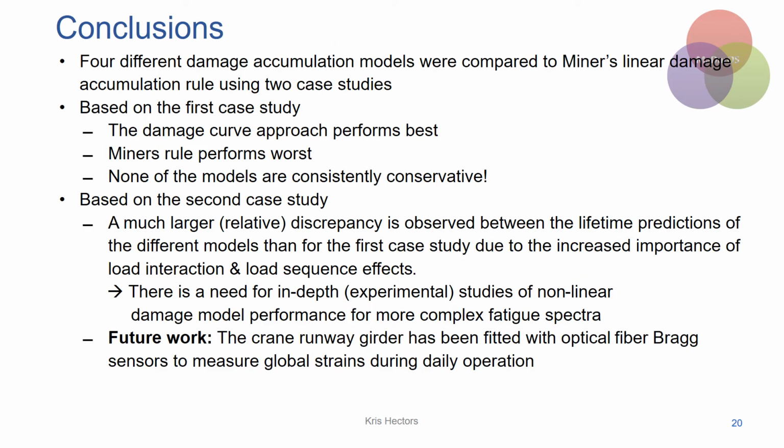To conclude the presentation, I will finish with a summary. We compared 4 damage accumulation models to Miner's linear damage accumulation rule using 2 different case studies. Based on the first case study, we found that Miner's rule performs worst and that the damage curve approach performs best, but none of the models is consistently conservative or non-conservative. In the first case study, no very large discrepancies were found between the different models, but this was definitely not the case in the second case study, where a more complex fatigue spectra was analyzed. This shows that there is a clear need for more in-depth studies of nonlinear damage model performance when complex fatigue spectra are considered.